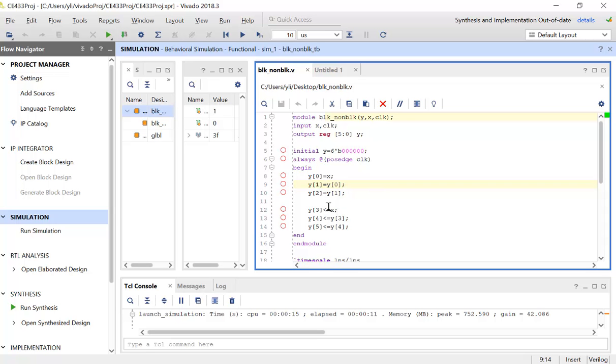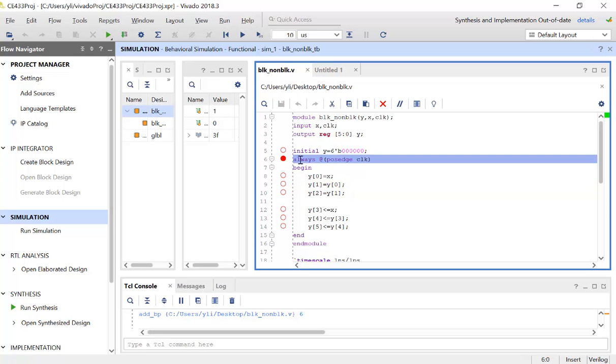So another question here is, if that's the case, why does this sequential logic work? It's sensing the clock and then updating the signal. So you have to have sequential circuits in there, or another way to say it, D flip-flops. Okay, you have registers in there, so you can update the entire digital circuit using different states.